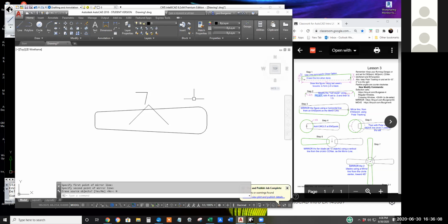Getting back to step 4, we know the diameter of the circle. That's what the circle slash means in the magenta circle /8. That means the circle has a diameter of 8. The circle slash is global language for diameter. I believe just about any Western country will understand circle slash means diameter. So let's drop down and select center diameter tool.